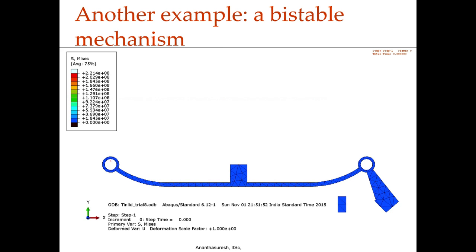So, you saw the tin lid where we could switch it between two stable states. One was just up and down motion that we just saw, the other was sideward motion. So, the bistable arch that I showed in the previous slides, let us look at that again. Here you see two pin joints, there is a pin joint here, there is a pin joint there. This actually is a cross section of that tin lid that we just saw. If you take a cross section somewhere, this now can be made into a planar arch.